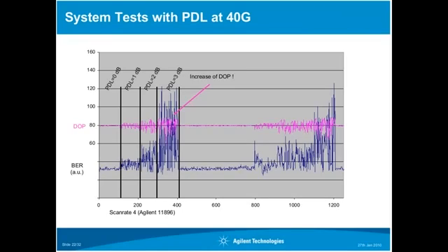Once you increase the PDL levels, you will see that the PDL is creating some change in the degree of polarization. You see that although the PMD level or the PMD distortion is not changing, you see some changes in the degree of polarization. And it is plain to see that actually if you have a PMD compensator, the PMD compensator is trying to work against it and trying to optimize this. So that is something you want to understand if you have a PDL problem on your link, because this is probably influencing the capabilities of your PMD compensator.